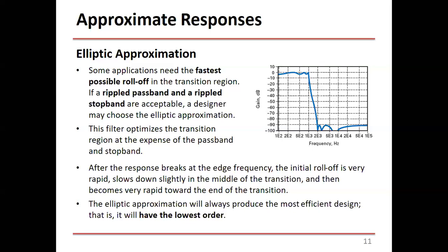Okay, but with an expense. This doesn't come for free, actually. Okay, so what's the expense here? The major disadvantage of this filter is the nonlinear phase. If you look at the phase of this one, but it's not shown here, if you plot the phase against the frequency, the phase is highly nonlinear. So if you are okay about the nonlinearity of the phase, which not all applications appreciate, some applications, maybe in communications or speech processing, it's not appreciated to have a nonlinear phase, and we need to have linear phase.